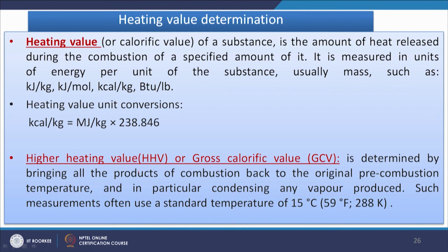Now, we will discuss heating value, when we are talking about waste materials. If we combust this waste material, it will be converted to flue gas, which will have a high temperature. When we use this flue gas to generate steam, the heat available in the flue gas will be converted to the steam, and the heating value is defined as the amount of heat released by the combustion of unit mass of the material.